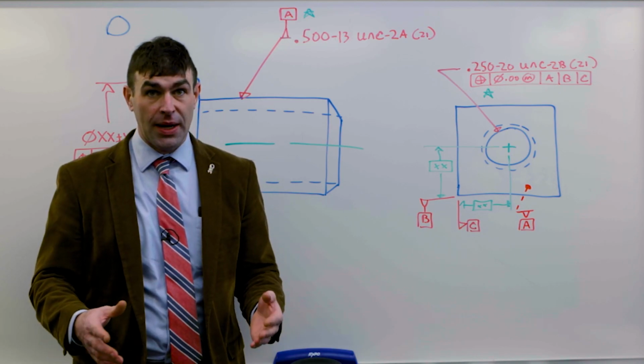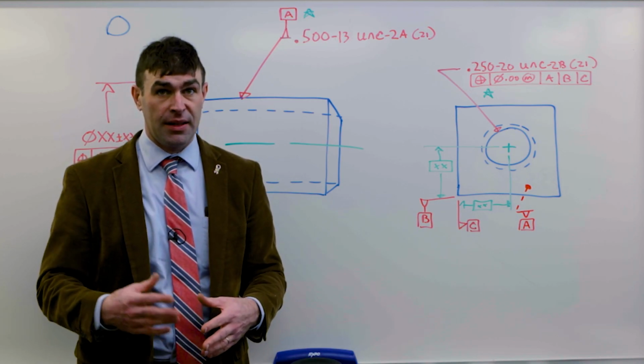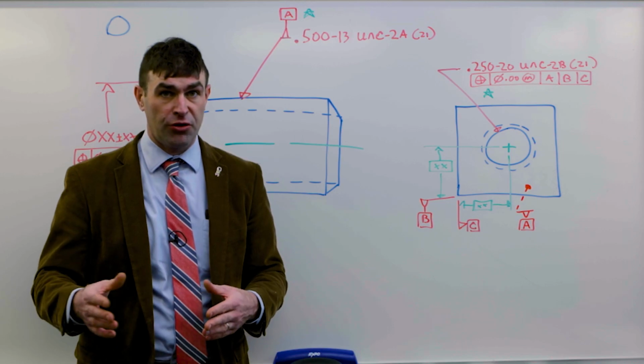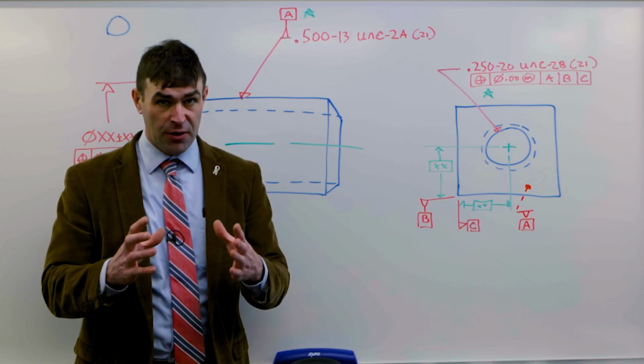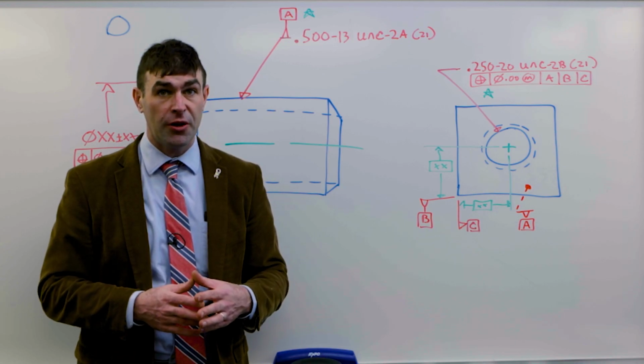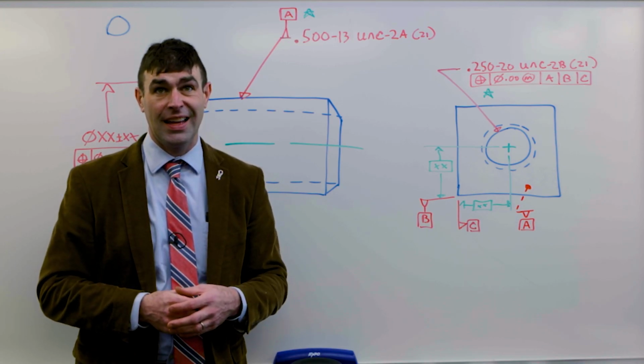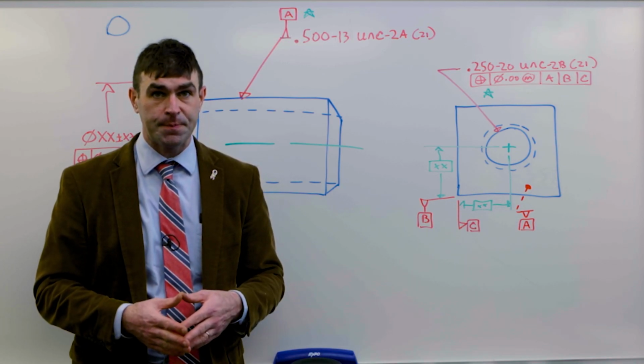Now for standard threads, it's not a big deal. They make special gauges for this, and in the later part of this video I'll show on the plate, that thread in and are meant to locate that pitch cylinder, and they've got a precision pin on the end so you can find that.